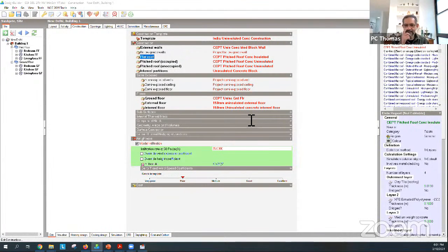Well, anonymous attendee, that is a very insightful question, and thank you very much for that. That's up to you as a designer, right? So if your building is what we call fabric dominated, that means it's the building envelope that plays a bigger part. But if it's what we call internal load dominated, then it's completely different. If you go to a data center, for example, a data center is full of computers producing huge amounts of heat. You actually don't even need a building. You just need a very thin skin around it. And the heat is trying to get out. Your air conditioning system is desperately trying to cool the space because there's so much heat being generated.